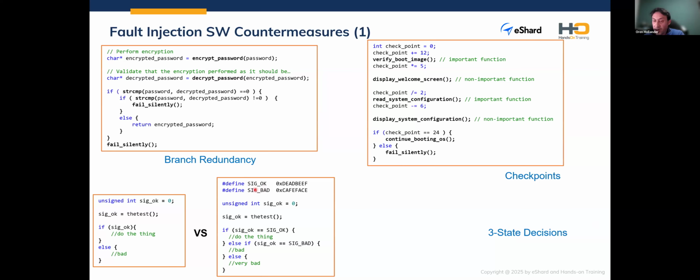to define or use, if you like, a non-trivial value to represent false, a non-trivial value to represent true, and all other values will represent false. The values representing true and false should not differ by a single bit. Otherwise, they can also be fault injected by one bit. So we know that with fault injection, it is possible to corrupt any non-zero value. Therefore, we can end up with a successful fault. That's why we actually have three options in the code. You see, we have if, else if, and else.